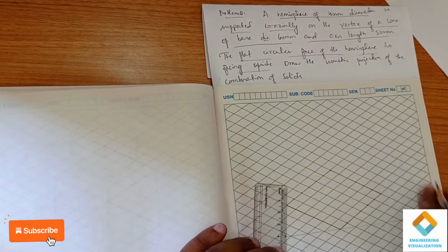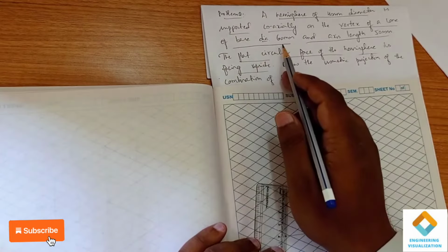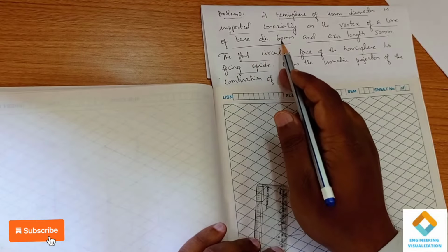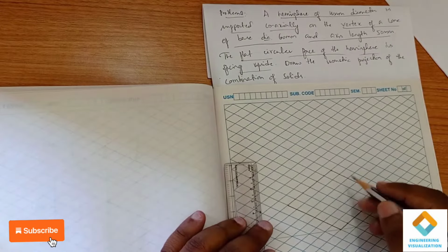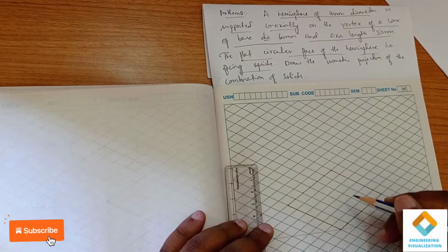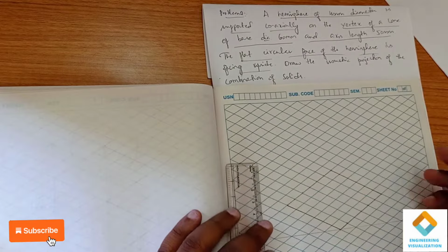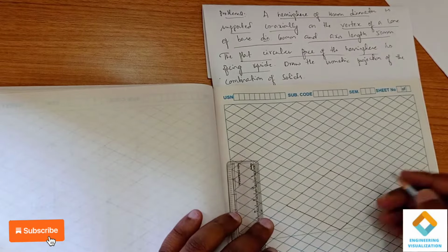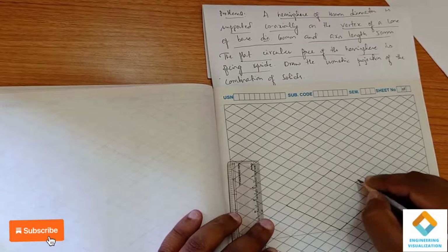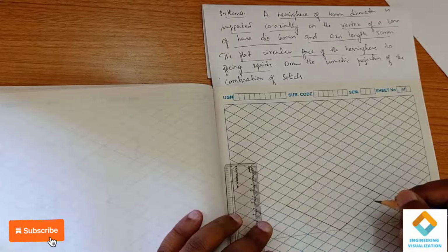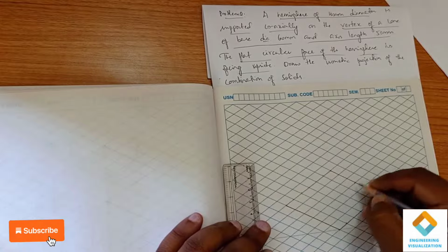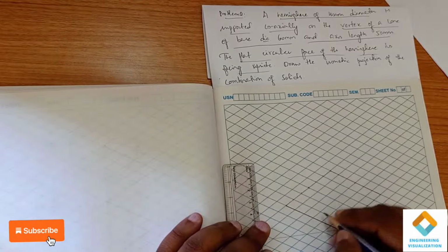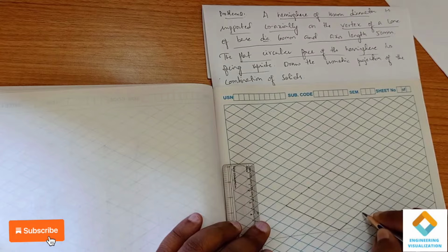Now you see that the base part of the cone, which is given with the diameter 60, is a circle. Okay, so when the circle is constructed in iso, it will become an ellipse. How to construct the ellipse, I will show. Here to construct an ellipse we have to go for the 4 arc by center method. First I am going to mark the middle point of all the edges. If it is 60, you can mark exactly at 30 here.